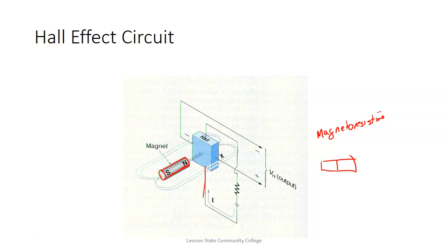these are electronic, so they've got to be powered up. And it doesn't make any difference. It's just that you got to make sure you replace it with the same type. So if you had a magnetoresistive sensor and you replaced it with a Hall effect because it was similar, then it probably wouldn't work because the magnetic field that it's detecting is not oriented correctly.